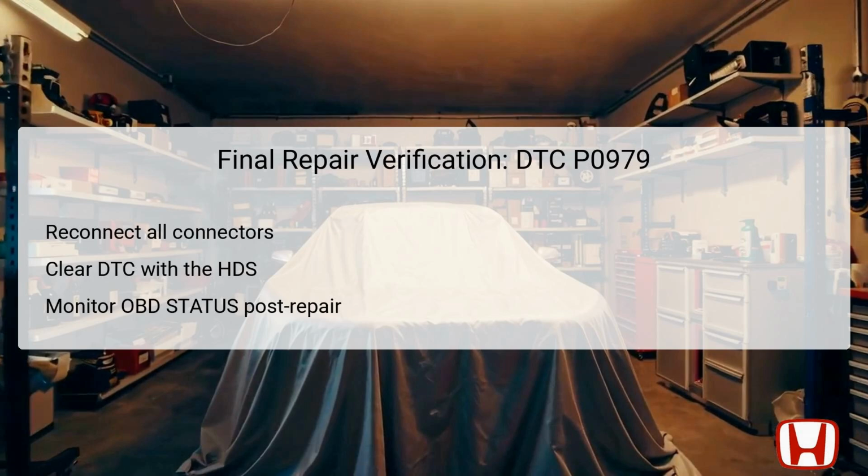The last step in the troubleshooting process is final repair verification to ensure the issue has been adequately addressed. Begin by reconnecting all previously disconnected connectors, ensuring they are secure and properly seated for reliable operation. After reconnection, proceed to clear the DTC using the HDS, eliminating any previous fault codes that may linger in the system. Start the vehicle with the shift lever positioned in park, P, and allow it to idle for at least 1 second to facilitate an accurate assessment of the system.